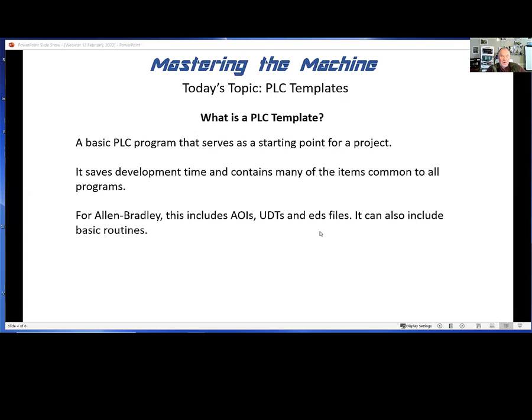I've mentioned this before. You get them from the vendor of the equipment, not from Allen Bradley. You don't call Allen Bradley up and say, I want an EDS file for a FANUC robot. You won't be able to get one. So you have to go to the vendor of the robot or the vision system or the valve bank or whatever it is that you want.